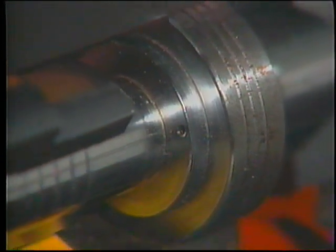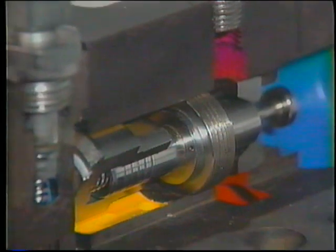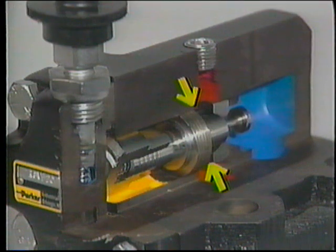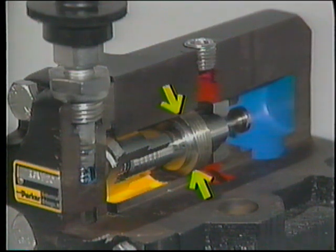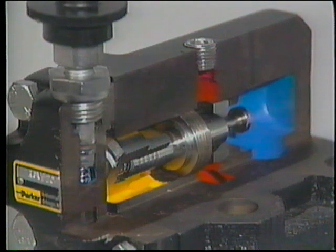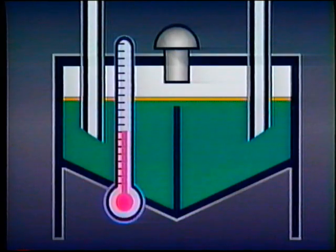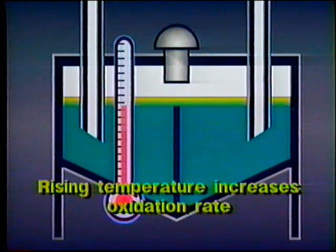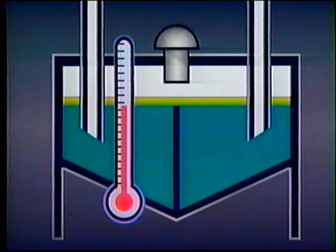paths. Proper operation of many components, like this pressure control valve, for example, depends on a close fit. If acids corrode the metal surfaces, clearances like these will increase, and the system may not operate correctly. Heat speeds up the rate of oxidation in a reservoir very quickly. Generally, oil oxidizes twice as fast as normal for every 20-degree Fahrenheit rise above an average reservoir temperature of 130 degrees Fahrenheit. Oxidation inhibitors can be added to the oil to slow the oxidation process in the reservoir.